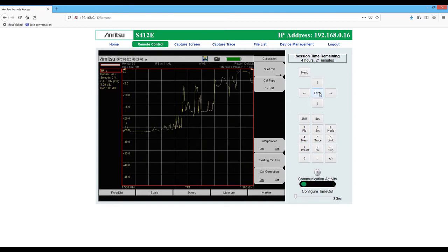And we could hook up any antenna and start making our measurements in return loss. Now, because we've calibrated for the specific frequencies, we can do any of the one-port measurements that are listed as long as we don't change frequencies. And I went ahead and put just a random antenna on here. And as you can see, this antenna is really good in the 1800 band and really horrible at 1500. And it's just a small little antenna, so no great things there.